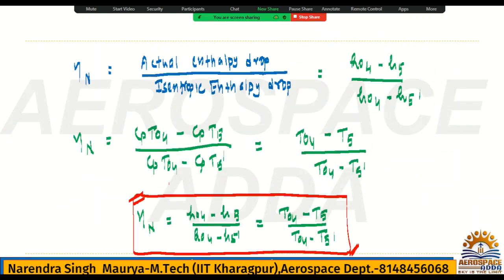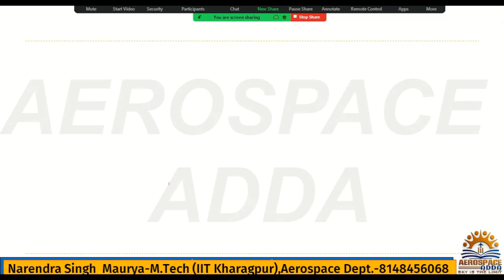Now the next level, I'm going to tell you when the nozzle is choked and when it is unchoked, and what calculation parameters will change for further calculation. Calculation parameters in the sense of what pressure and temperature you will take for the choked condition, and what pressure and temperature you will take for the unchoked condition. Because, as I told you, the nozzle is a very important component of the engine: in the nozzle the more and more expansion you get, meaning all the pressure energy available in the engine is converted into kinetic energy. So you will have the highest exit velocity at the exit of the nozzle, and then obviously you will have the maximum thrust. For this reason we need to check the choking and non-choking condition.